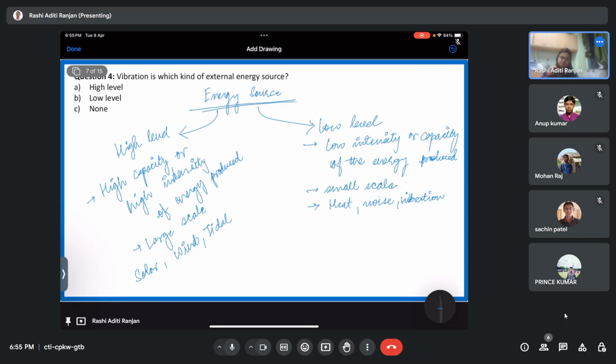So in that case, instead of just letting it get wasted, we can use it. Like I told you, piezoelectric material has the capacity that if I deform it, it is going to produce voltage. It is going to produce charge, right? So if one of my machines is vibrating, what can I do? I'll apply a piezoelectric patch on it and connect wires in such a way that charge can flow. Then I can store the charge maybe inside a battery.